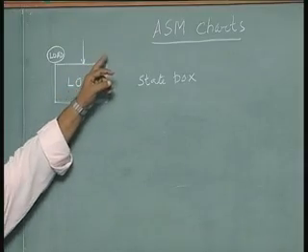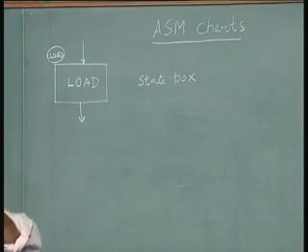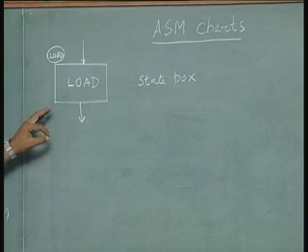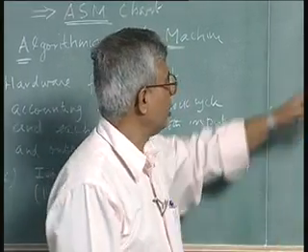And on the right hand top corner, again outside the state, you give the binary state assignment. Each state in a state graph needs, depending on the number of states, a number of variables, and each of those variables will have a 0 or 1. So you have a binary number representing each state, and that number is given here.